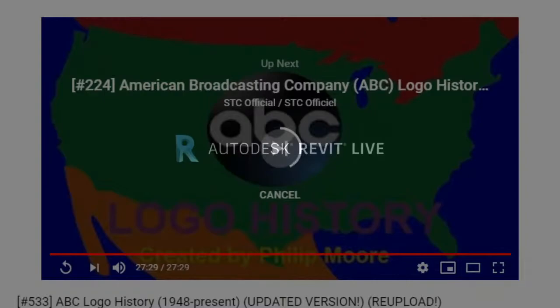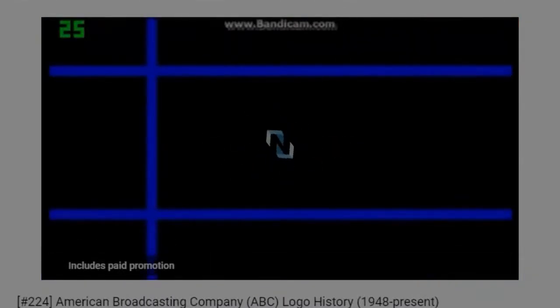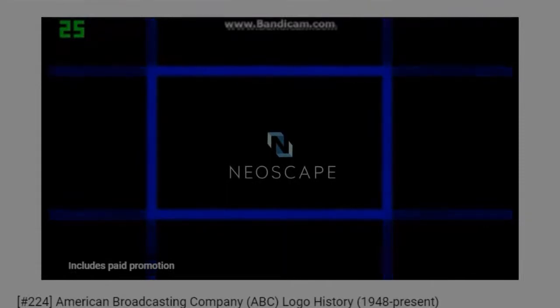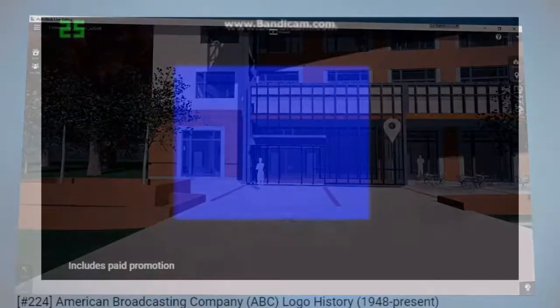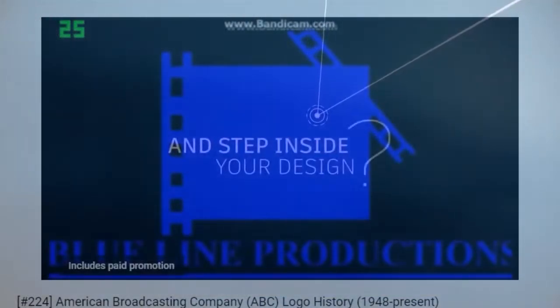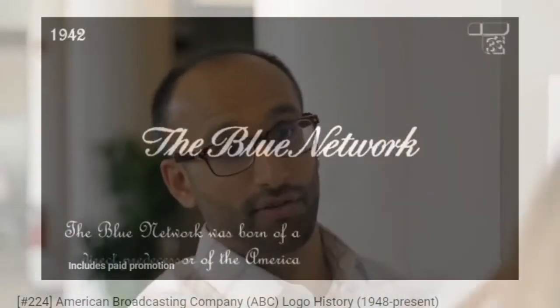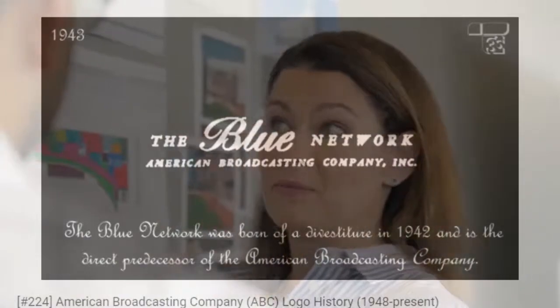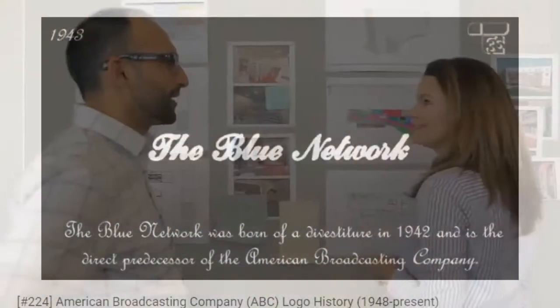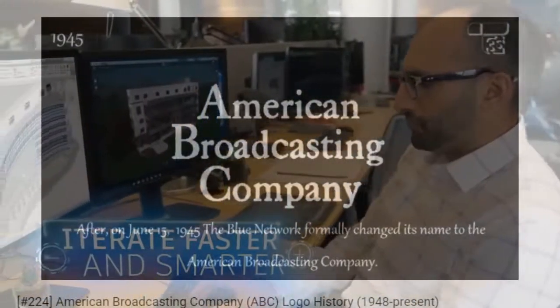You can apply a great deal of flexibility to a floor assembly in early design. As we described previously, you can create a floor for early design phases that accommodates the floor structure, plenum, and ceiling in a single floor type, and we can create soffit conditions at the exterior walls. So that's going to be important. Let's run through a short exercise so you can practice this skill. C14 Design Floor, which we have open from the book's web page, or continue with the file from the previous exercise. Select the floor at level 1 and open the Properties palette.